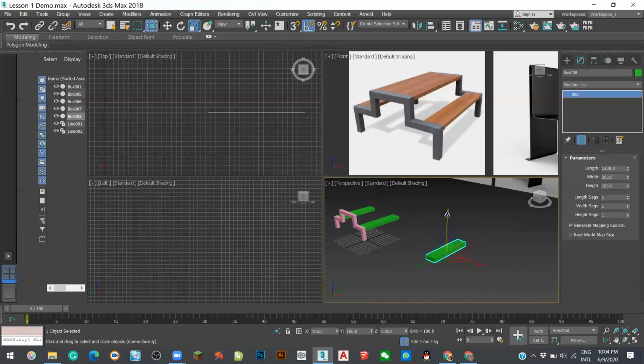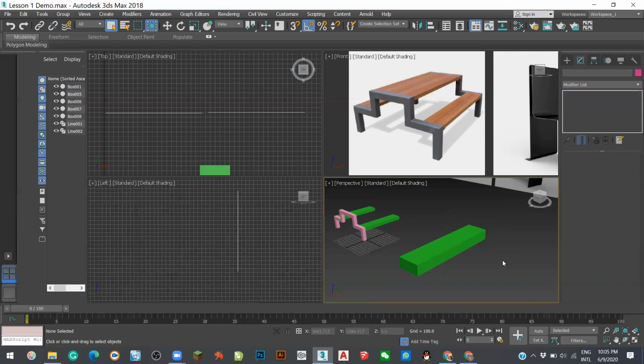For the scale also, click this. For example, you want to scale more thick, you use this one. Wider, use this one. Longer, use this one. But you will see, once I change this one now, this parameter won't change. So you wouldn't know what size you changed to already. So we better don't use these scales to scale up, or you just want to scale a little bit, like sofa, cushion, bed sheet, all these non-countable decoration objects. Okay, if let's say for the furniture, the wall, cabinet, all this, we better change on this modify. Okay, I undo this.